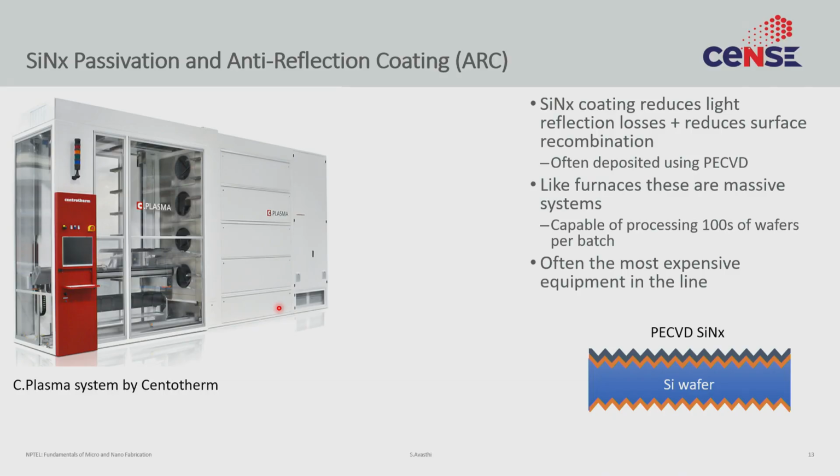But again, this is very different from the PECVD that you have probably seen in your research facility or would see in an Intel fabrication system. These plasma systems are huge. They look like this, so they look like furnaces. In this case, there are 4 different furnaces. Each of these is actually an RF deposition system. Now, in order for it to be an RF deposition system, you can imagine it requires electrodes, right? So how do you load 400 wafers and provide electrodes to each of them?